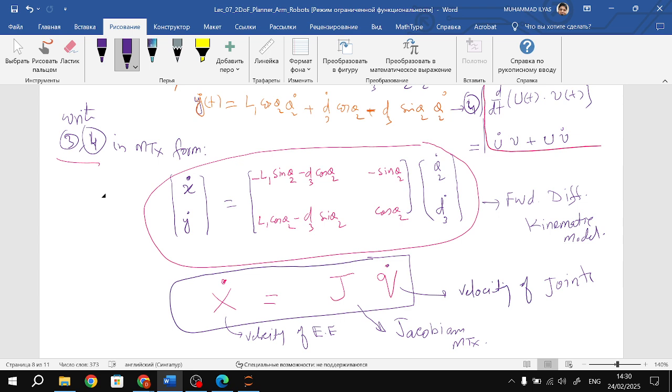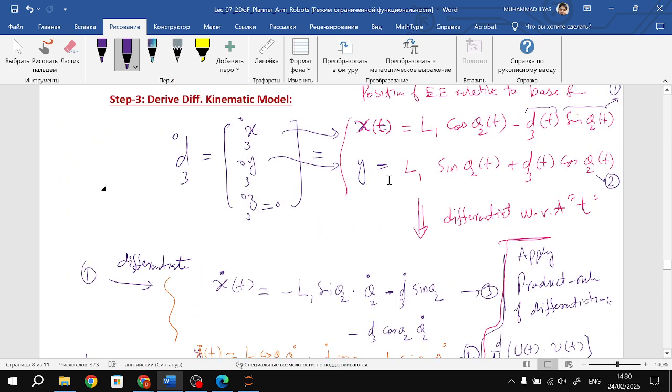Easy. So it means that first you find the forward kinematics and find the position vector, which is the d3 to 0 in this case. First, we find this by multiplying all the HTMs, and from there you have the x term, y term, z term. The z term is 0 in this case because we are dealing with planar robots. But in the next classes, like when you study robotics manufacturing 1, we'll study 3D or 6D manipulators where you have all the x axis, y axis, z axis, and then the angles in x direction, y direction, z direction.